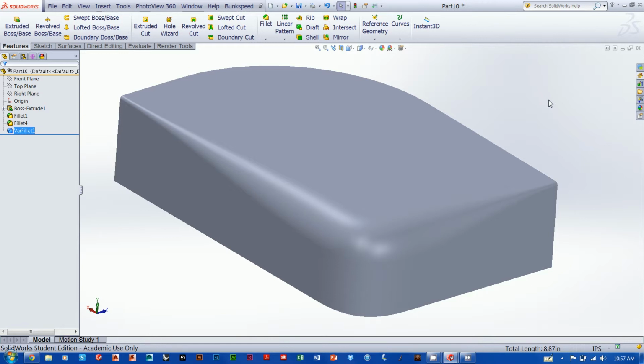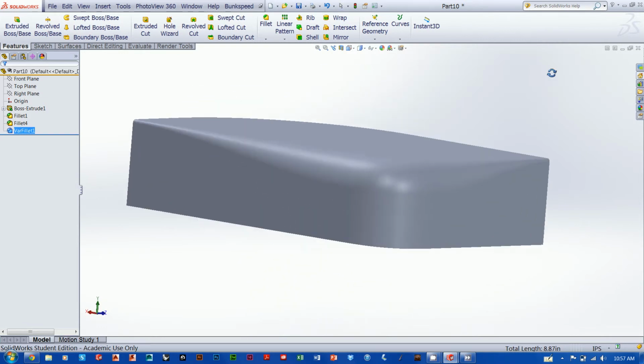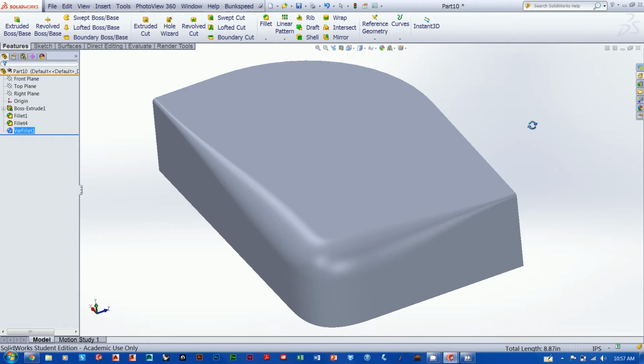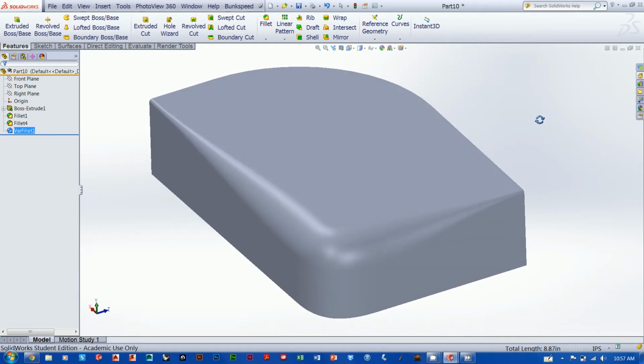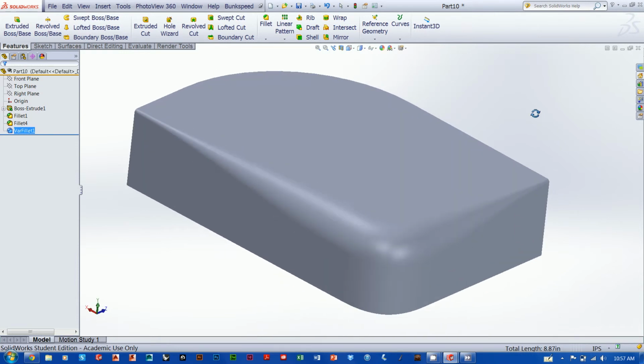How your products produce reflections and handle light on the surfaces that you're creating really defines whether you're a good 3D modeler or not, and tells a lot about the quality of your skills in 3D. And so hopefully you won't ever find yourself in a scenario where your client asks you to do something like this. But in case they do, or if you find yourself needing to have a fillet that expands from one size to another, variable radius fillet will do the trick.